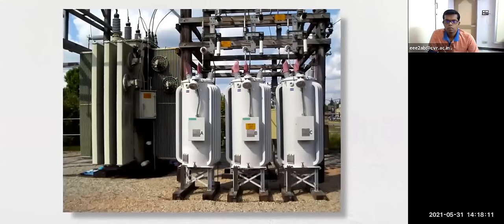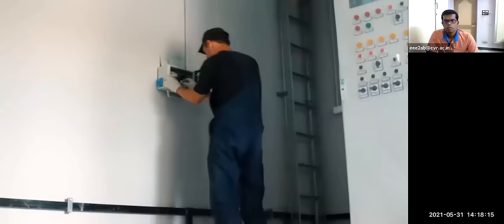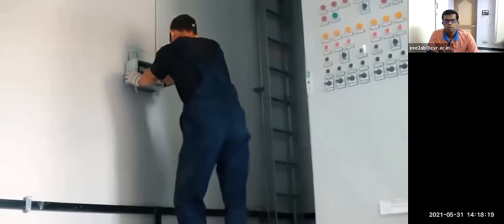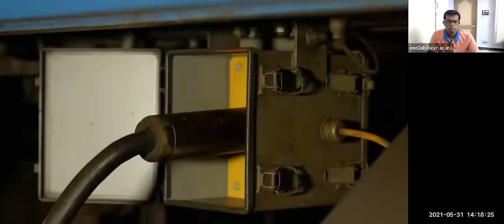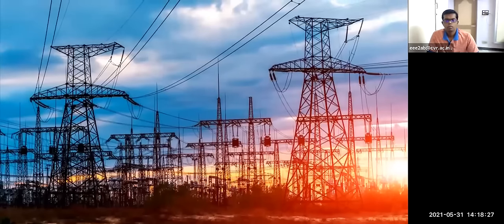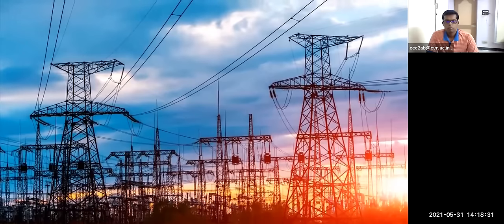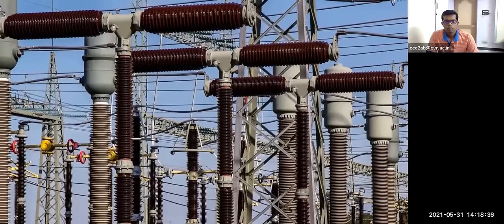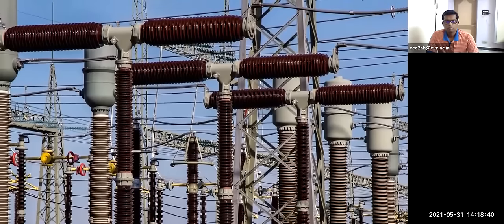If you look closely, you can sometimes see the regulator dial indicating the tap position. All that different equipment requires lots of maintenance. The final and most important role of a substation is that it be safe for electricians and linemen to inspect, repair, and replace equipment. Substations are usually the only locations where extra high voltage power lines get close to the ground, so safety is absolutely critical. The buswork running along the substation is protected from short circuit by large insulators to avoid arcs to ground.